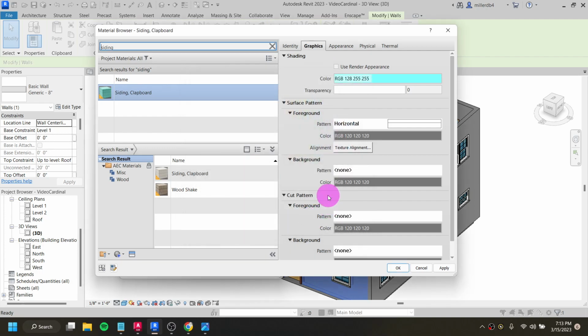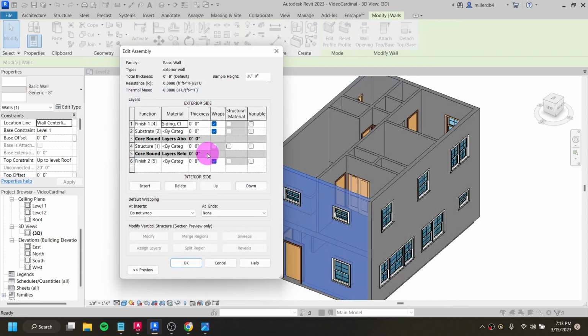So I'll have it be this fluorescent teal, and it'll have horizontal stripes on it. So I'm just going to click OK. And then I'm going to define a thickness of our siding. So I'm going to make my siding 3/4 of an inch, which I could type in here a couple of ways. What I usually do is just only highlight the inch amount and then put my inch in. So I said that this is made out of clapboard siding. It's 3/4 of an inch thick, and we can see that it's calculating an R value based on the physical properties it knows about clapboard siding.